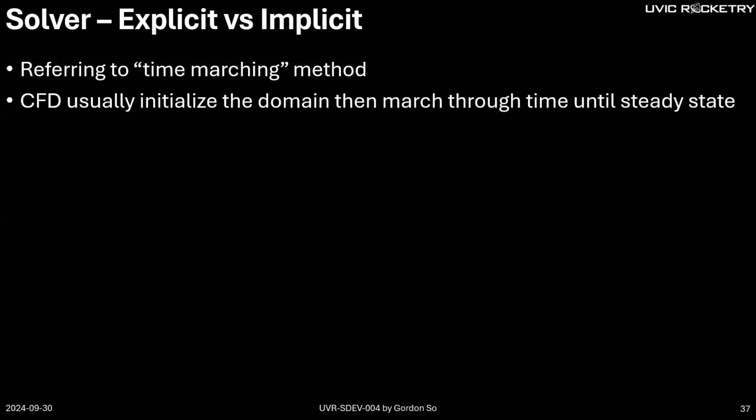Usually, you need to make your cell small enough to capture certain flow. Again, it depends on what kind of flow regime you're looking at. Supersonic flow may want a more detailed setup. You may need to refine your mesh more.